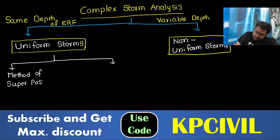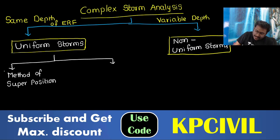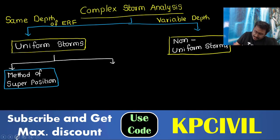Superposition. Using this method of superposition, you can divide a complex storm into n equal number of simple storms. I am taking the total complex storm duration T divided into n equal values of D hours.